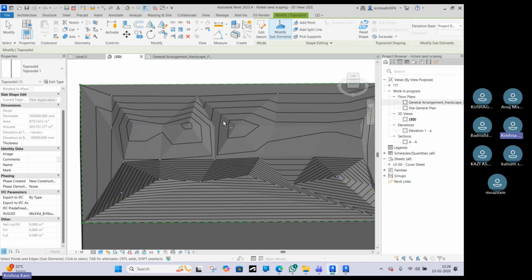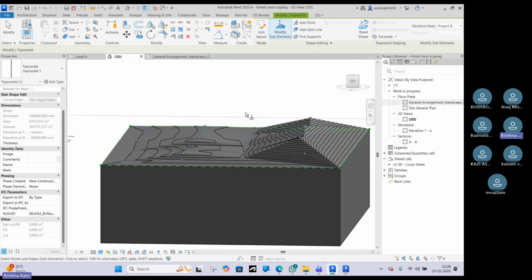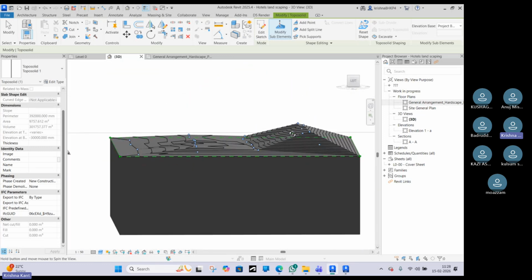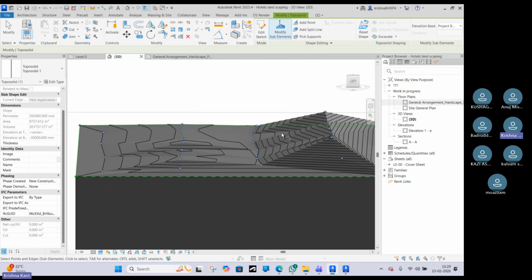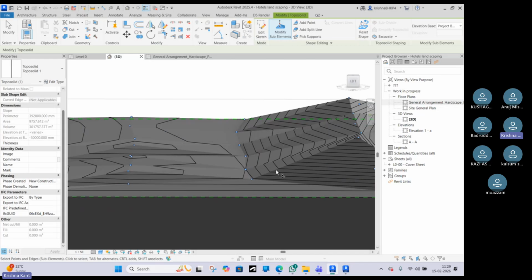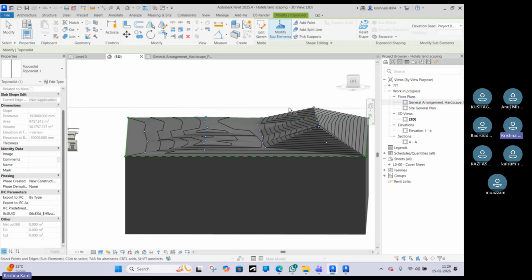Because in this element, if I do a certain area plane, based on the plane, I want to describe a certain area for our plot so that it will be flat. Now I have to check, while flattening a certain area, how much soil we have to cut or how much soil we have to fill. For that purpose we have to do graded region.